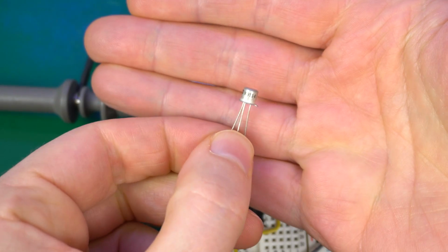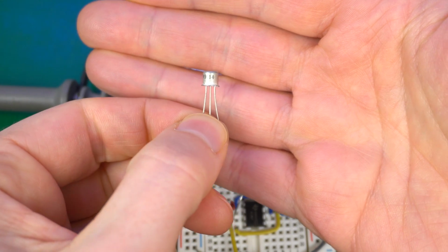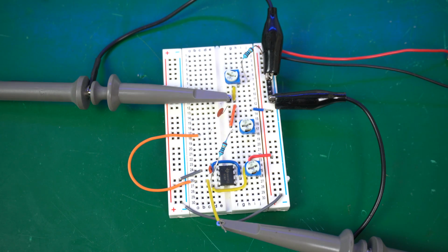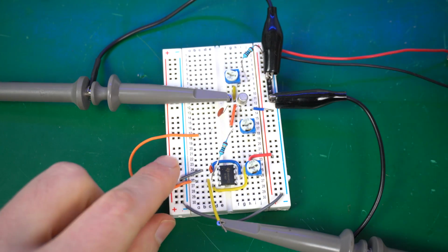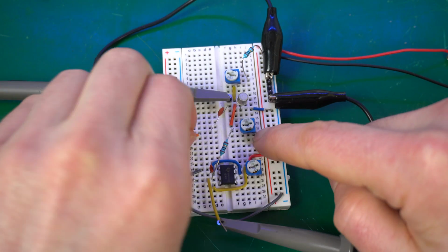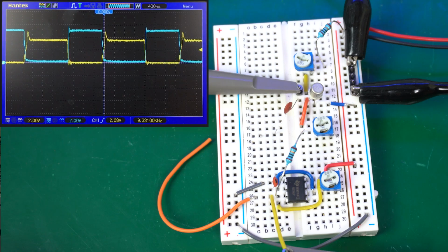Before taking all of this and putting it on the Amstrad board, I want to run some tests with 2 other transistors. The first one is called 2N2369 and has this funky rounded body that I hadn't seen before. Someone in the comments suggested that this was a really fast transistor and it might be a good replacement for the original one. Since I had a few spare ones because it's present in the Dragon 32, let's see how it behaves in this setup. And with this one, wow, it's just a matter of turning it on and instantly we get a perfect inverted square wave. It looks like this one is a perfect match for the original transistor as far as this circuit is concerned.